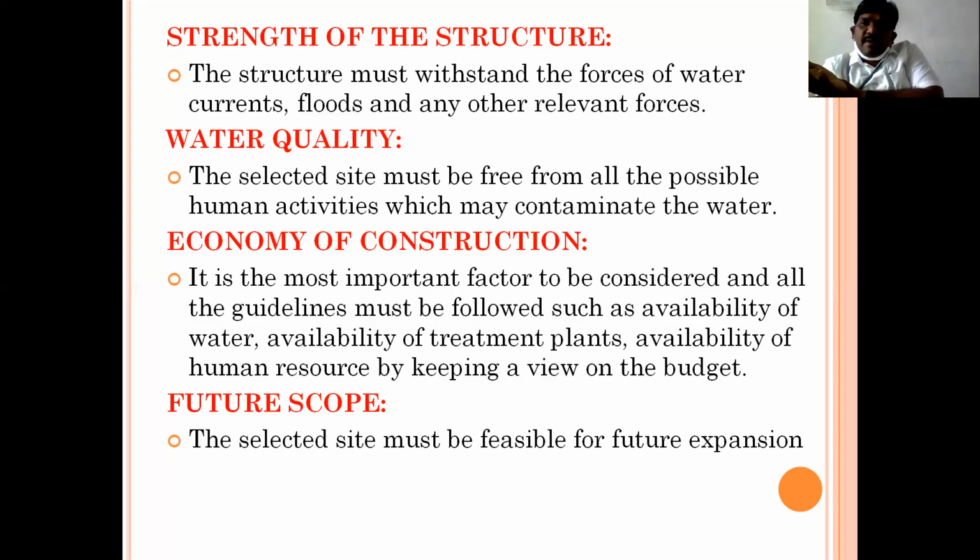If you are imposing a high amount of money for supplying water, it is not economical, it is not user friendly. That is the reason the structure must be at river banks, but we must be in a position to select the site where human activities are minimal or less.